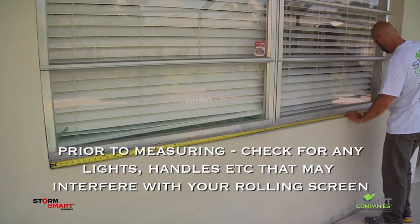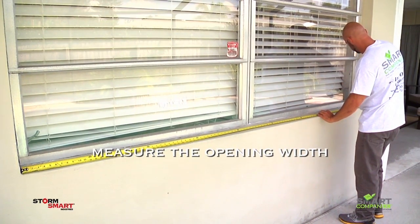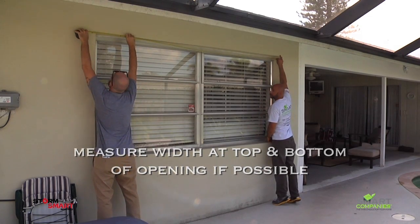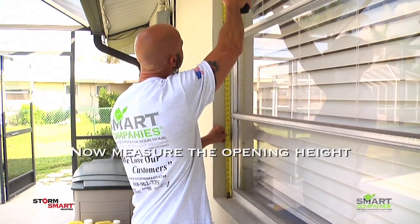Our opening in this video is a concrete substrate. First, measure the width of the opening. Note that we recommend measuring width at both the top and bottom if possible, just to ensure that the opening is not out of square. Next, measure the height of the opening.